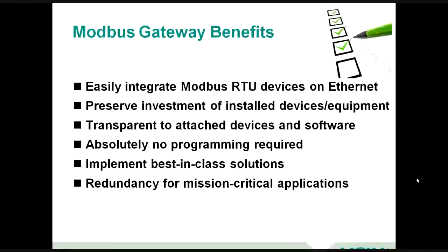And one part that I didn't have a lot of chance to go into is redundancy. Understand here that the gateways will actually support multiple hosts talking simultaneously to that shared serial asset. Where I had the ModScan software simulating a SCADA host, that gateway has the ability to be a traffic cop, and I could have up to 16 different hosts talking to it at the same time, and it'll multiplex between those, meaning it's really easy to have redundant SCADA hosts on Ethernet.